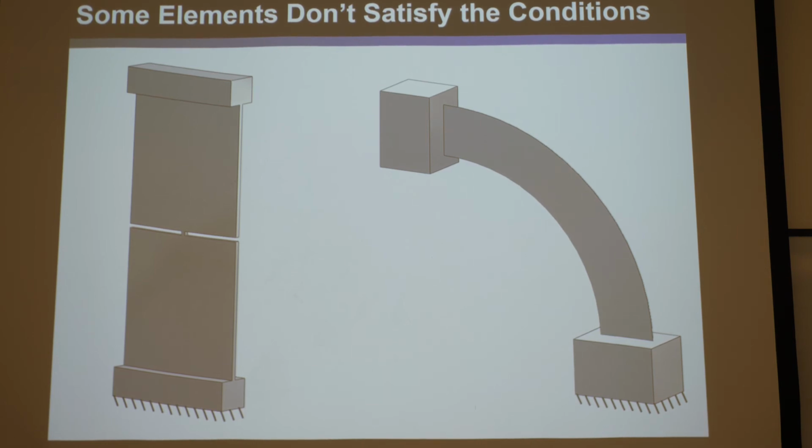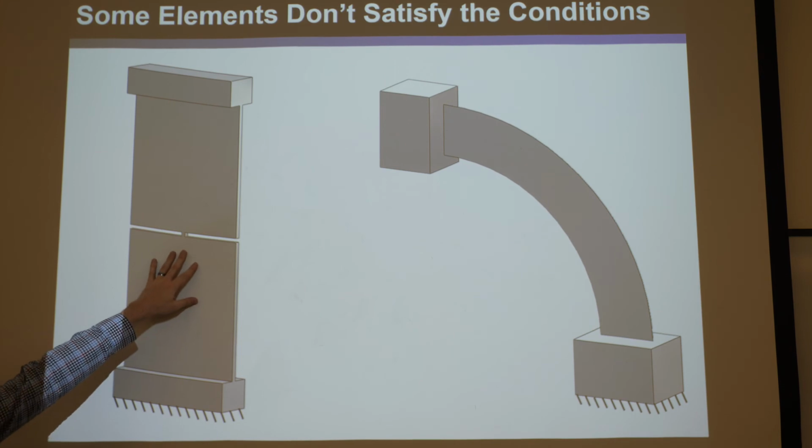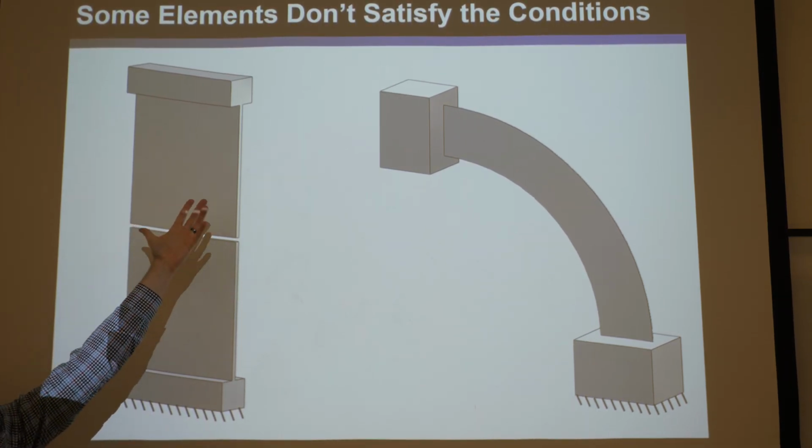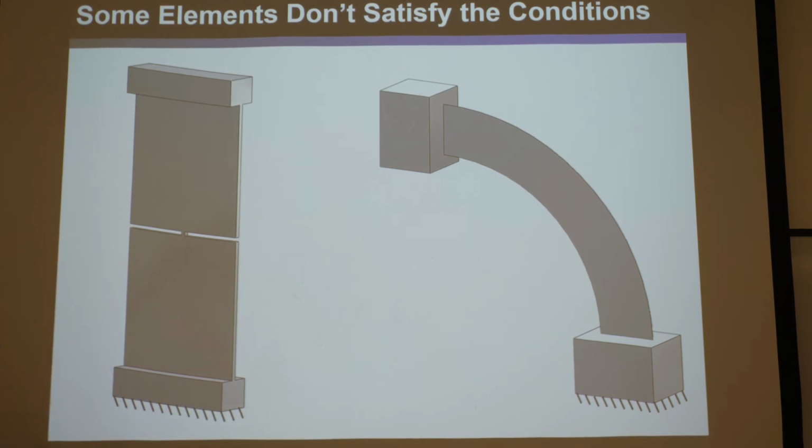But anyway, here is an element. So ask yourself, is this parallel? Well, you might say, no, it's obviously a blade flexure stacked in series with a nub flexure stacked in series with another blade flexure. So you can obviously see it's three parallel elements stacked in series. That should be one clue, but don't follow that clue. Ask yourself if it fits the parallel condition. That's a much safer way to do it.